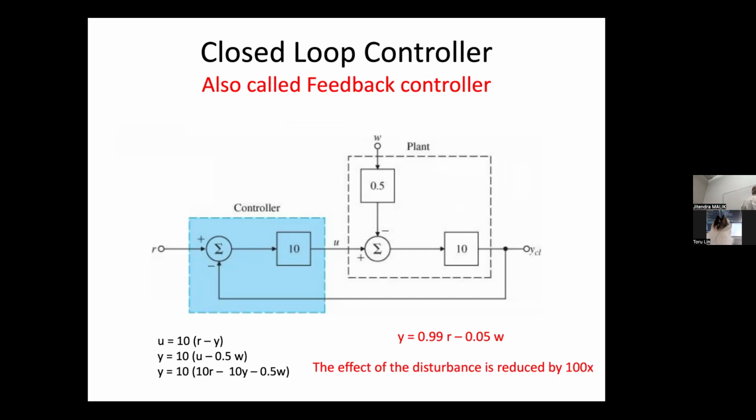It's very important here that you have a way of measuring the output, and you have your desired output. The desired output is R, the actual output is Y, right? So you've got this block here, with this differencing happening between R and Y, because you have the ability to measure the output. This R minus Y is an error, right?